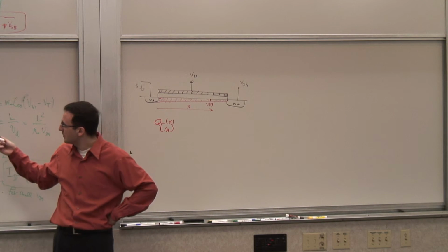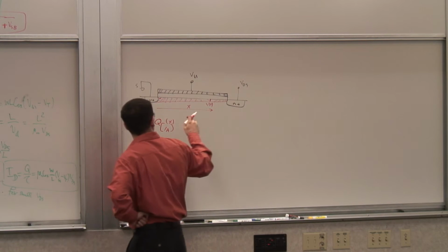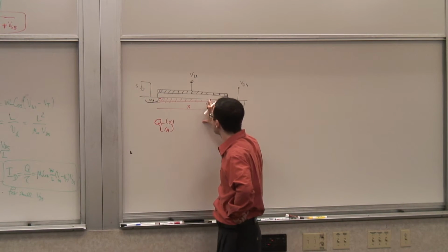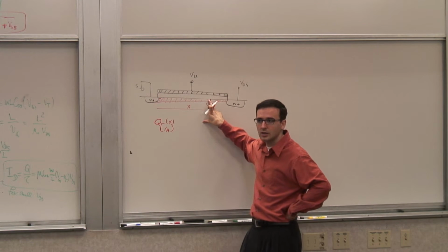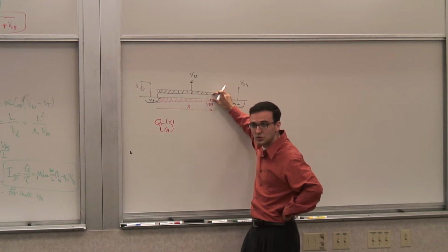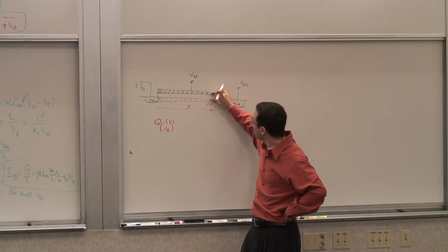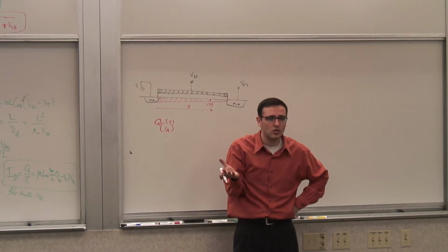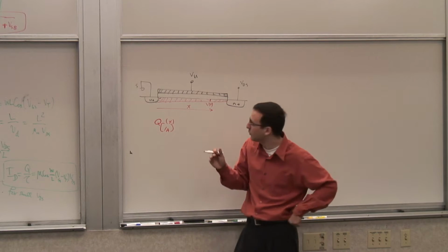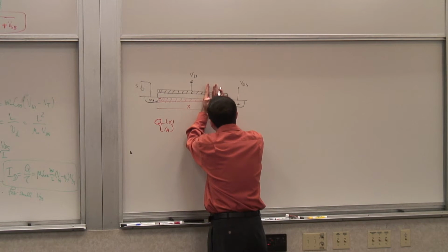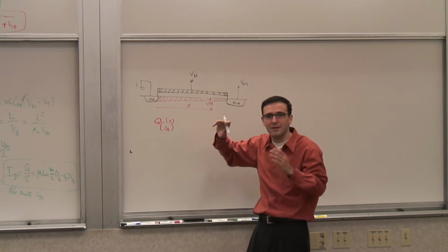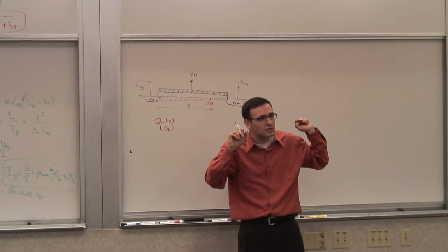Well, think about this. If my source were, instead of being whatever, this is my new source, right? This is like a little source here. So the voltage difference between these two, whatever voltage difference you have in excess of Vt, that determines my excess inversion charge at that point. If you look at it locally, it's like a little transistor. So you have a voltage here, you have a voltage there. This difference is my VGS for that point.